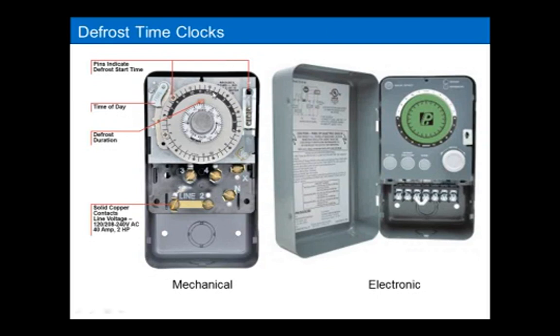So as a backup, I'm going to set this dial right here, so that if for any reason my defrost goes to this period of time, whatever that be, 35 minutes or 40 minutes or 50 minutes, if I'm in defrost that long, something's wrong. This time wheel here will then terminate defrost based on time. So this is kind of like your backup, where if your heaters are on too long, something's wrong, and you want to be safe and shut it down even though your normal termination method is not working. So this is your termination based on time, and typically it's used for backup.